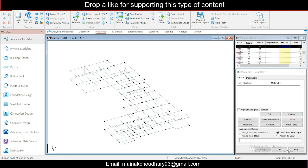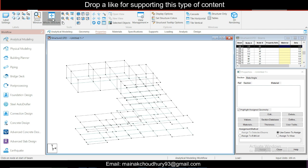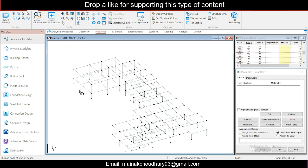Okay, so I'll join all the columns one by one. It's important that you go to view and display whole structure, just to check whether the points which you're selecting are okay or not. Otherwise you'll not know which points have intersection and which don't.